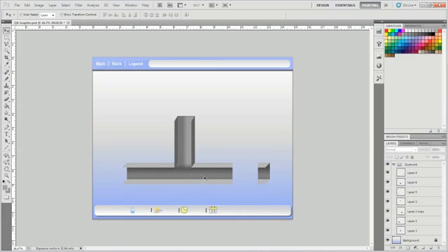Our library contains a couple different lengths of ductwork and pipe, but sometimes you need to stretch it to get to a desired length. To do this, simply select the ductwork to be stretched, grab the handle, and drag to the desired length, and then hit Enter.